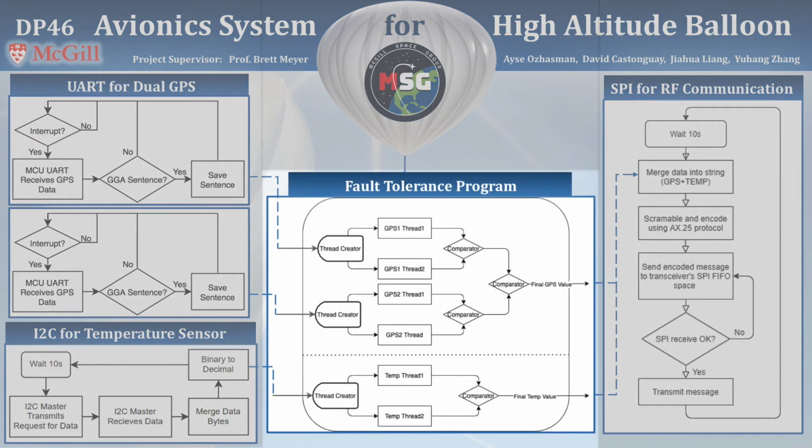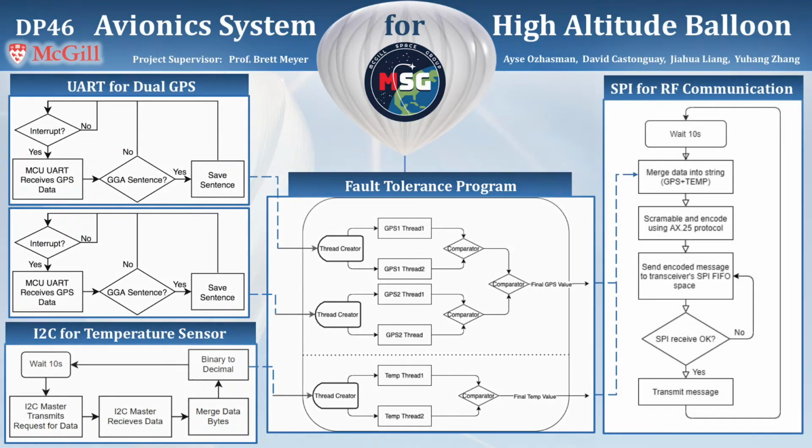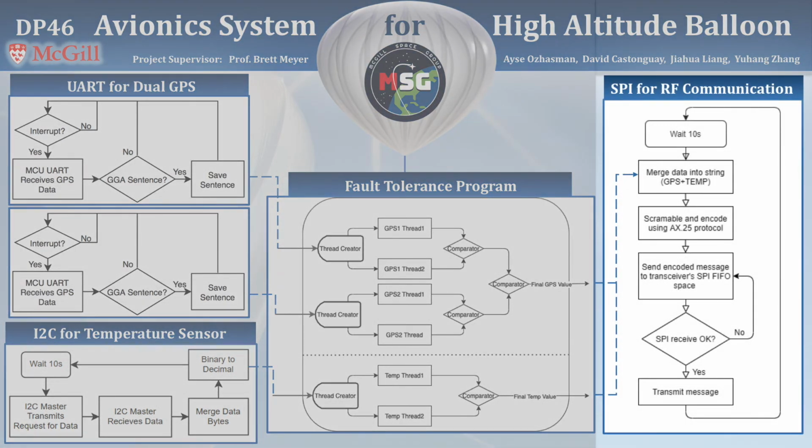The fault tolerance system detects faults by running redundant copies of the same program and raises concerns from the comparison of results. It replicates the sensor reading into 2 independent thread streams, and each thread is conducted sequentially by the system. The comparator will point check the thread results and raise an error if the result comparison ratio exceeds an error threshold. The last component consists of the communication thread.